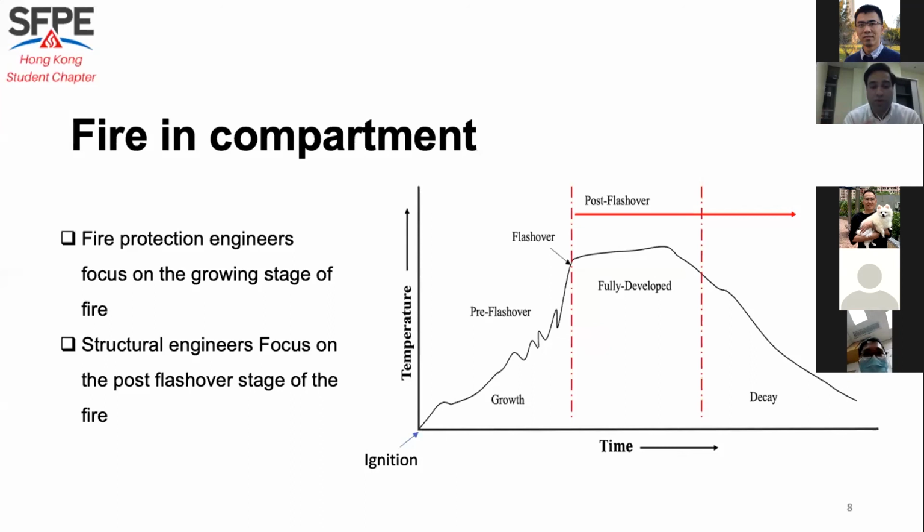But when we talk about the structural engineer, this growing stage is not very important. First, the temperature will not be very high here. And secondly, this is a very short period, maybe 2-3 minutes for a small compartment. So before it reaches flashover, maybe structural components like solid bodies will not be heated within this short period. So this is not very important for a structural engineer. They are mainly focused on the post-flashover fire situations or the fully developed stage.